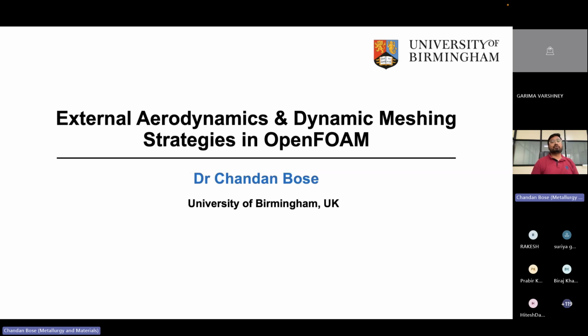Basically, this last session of the training was designed to give you an overview of different dynamic meshing strategies, mostly to be used in external aerodynamics and fluid structure interaction problems. I will try to give you a brief overview of all the different possible dynamic meshing strategies available in OpenFOAM. Mostly these are available in all three forks of OpenFOAM: openfoam.com, openfoam.org, and also Foam Extend.